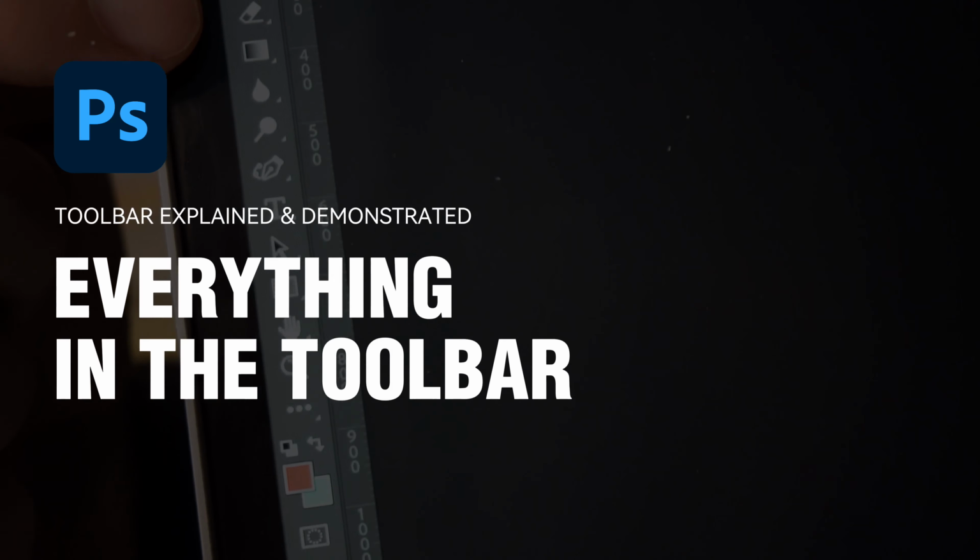Feather in Photoshop refers to soft edges. You can also make a feathered selection. For example, I want to change the sky color of this image. It won't work if I just use the rectangular marquee tool or any other marquee tool without making a feathered selection.